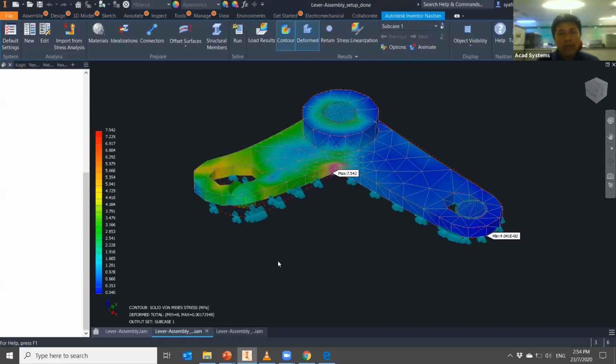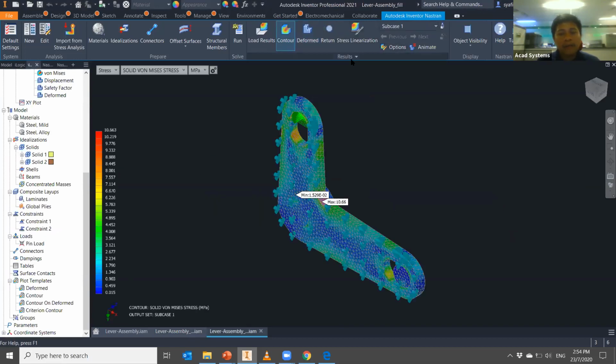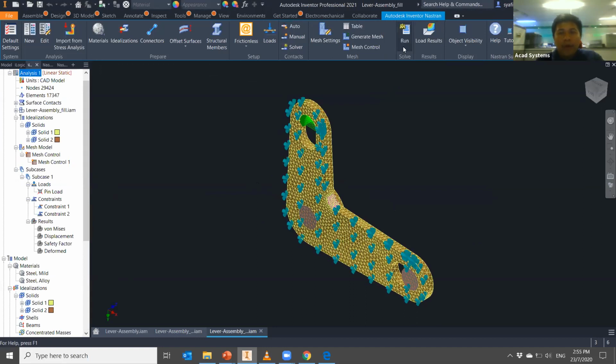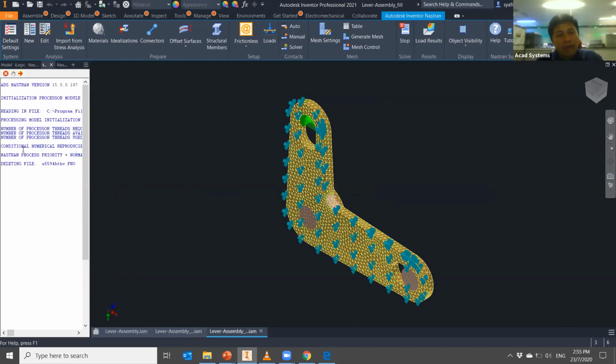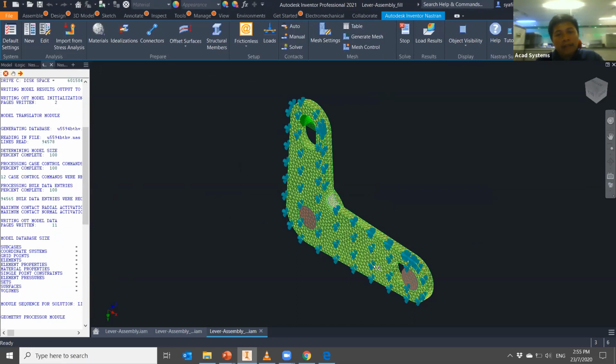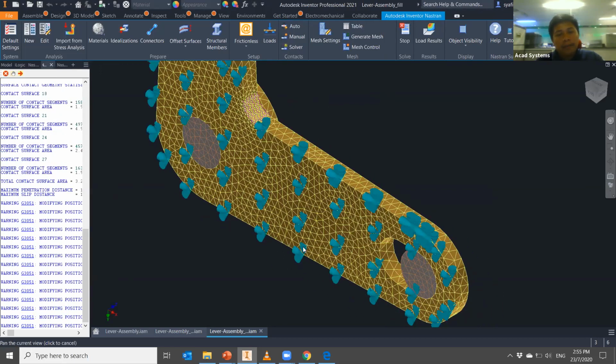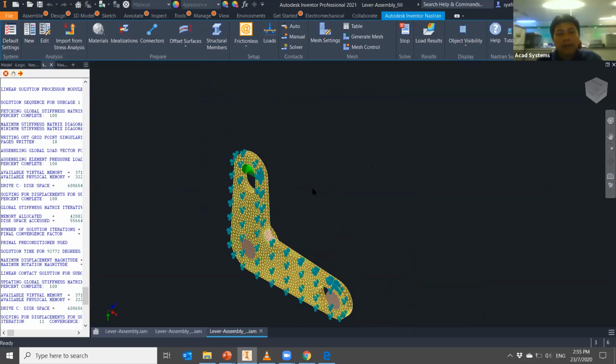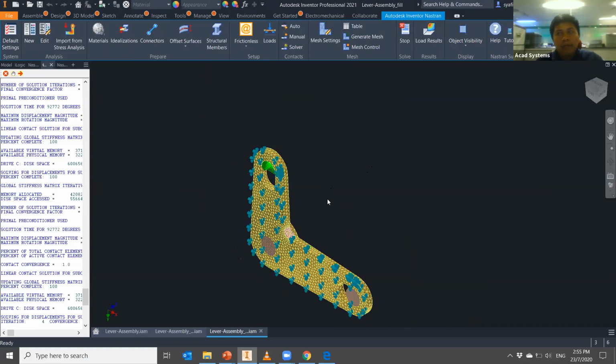Okay, so I show you once about our sample. For this type of simulation, it will take around 30 seconds to 1 minute to generate the result. While waiting for this result, what can I say over here? This will be the simplified method to get to know about your product strength, or to get to know where the part will fail first when load is applied.